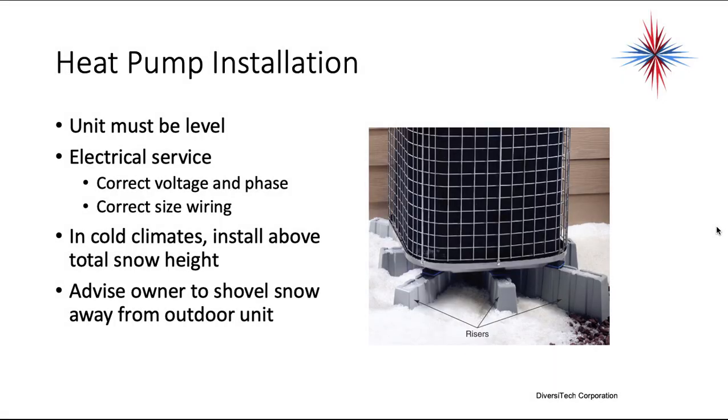Heat pump installation is actually pretty critical. Now, this varies a little bit based on the part of the country you're in. This picture is more for the northern part of the country where there could be snow accumulation. In the southern part of the country, you would never see the heat pump on risers. As a matter of fact, it's not legal in the state of Florida. The unit must be level. Electrical service, you have to have the correct voltage and phase, correct wire sizing.